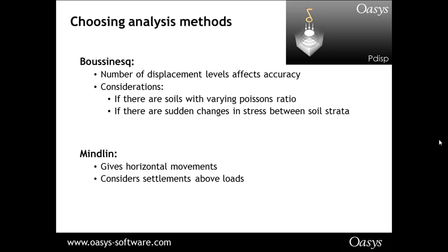With the Mindlin method, it's very good in terms of it gives horizontal ground movements, and it does consider settlements above loads, which the Boussinesq doesn't do. But just be aware of its limitations as well, and have a look in the manual for that.